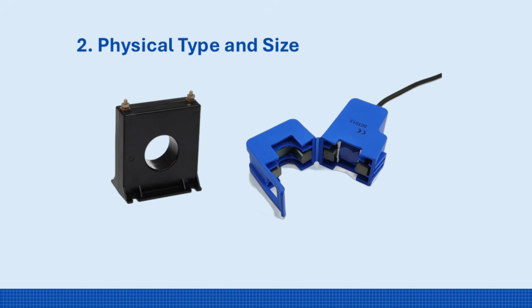2. Physical type and size. Solid core: highly accurate and tamper-proof, but requires disconnecting the wires to install. Best for new installations. Split core: hinge design that snaps directly around existing cables without powering down. Excellent for retrofitting. Window size: the inner diameter must be large enough to physically fit around the target conductor safely, but it should be as small as possible to ensure accurate readings and reduce interference.